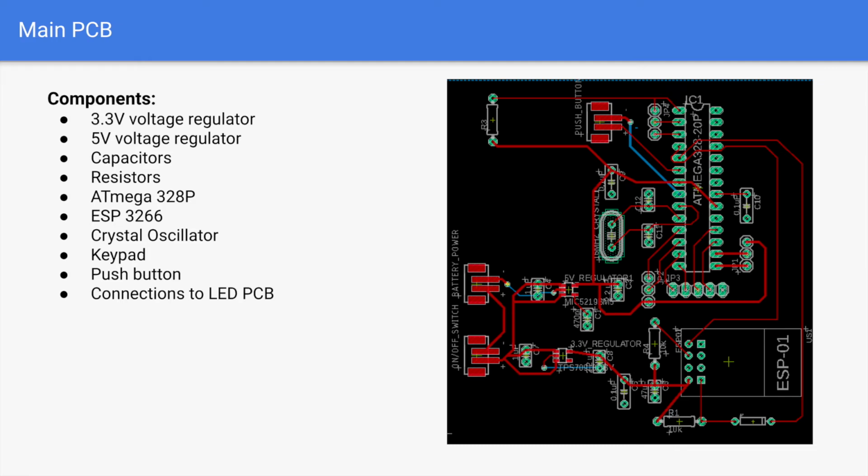We use through-hole capacitors and resistors for quicker assembling. However, the 2 voltage regulators are surface mounted since these were the regulators that met our requirements, making sure that the enable pin of the regulators goes to the input pin. When designing the board, we made sure to avoid 90-degree angles on our traces and to increase the width of traces carrying supply voltage. We also created a ground plane on the bottom layer.